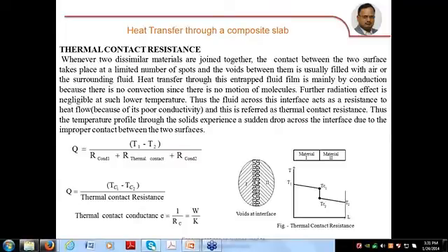So whenever there is a resistance for heat transfer, obviously there happens a temperature drop. We have seen earlier also, if the resistance is 0, which is an ideal case where thermal conductivity tends to infinity and the temperature gradient will become 0. Here at this interface the resistance is maximum, because the formula for resistance is del x by Ka.